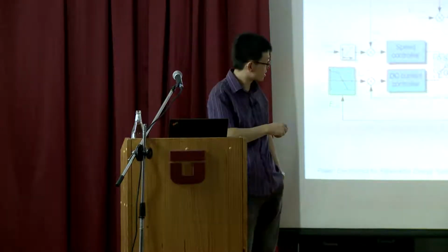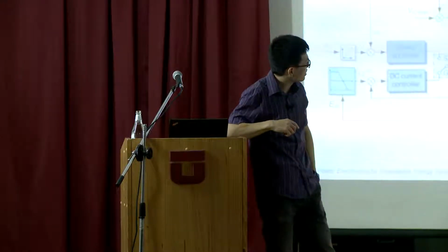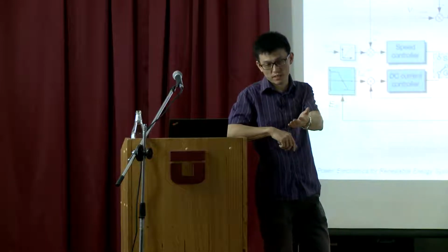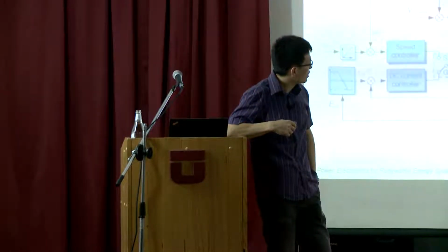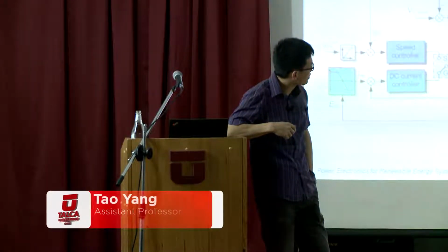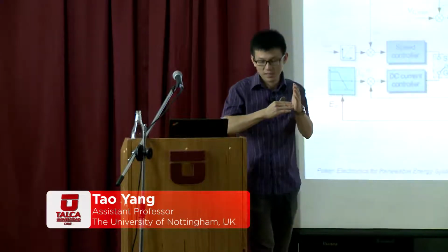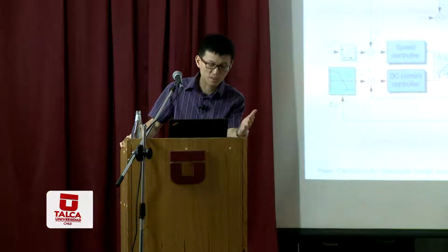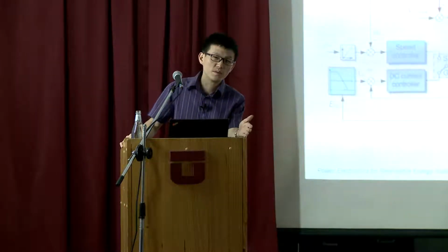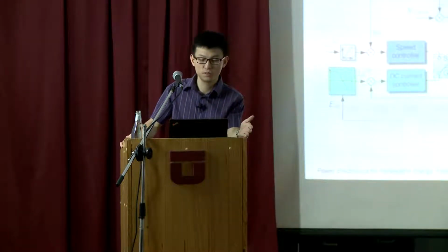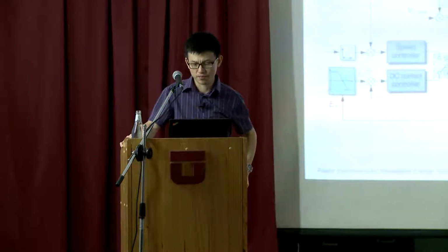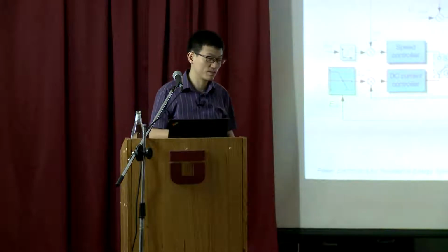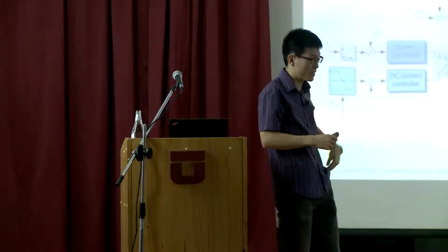And the idea of vector control is exactly to align the voltage vector, so to decouple the AC motor. We are going to control an AC motor as simply as a DC motor. Mathematically, what we do for vector control is decouple the current into two components.